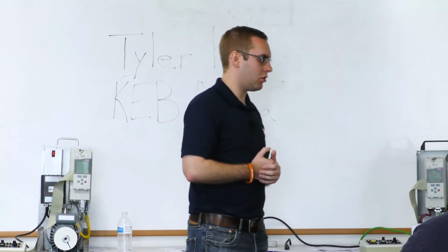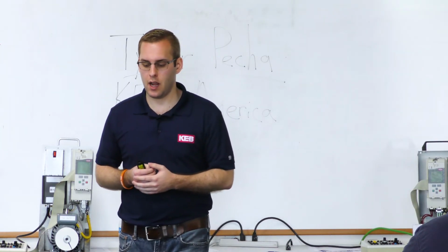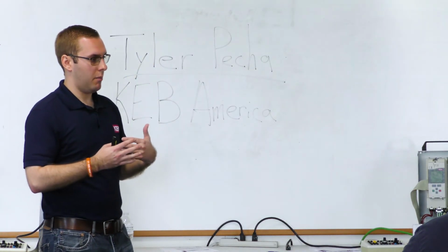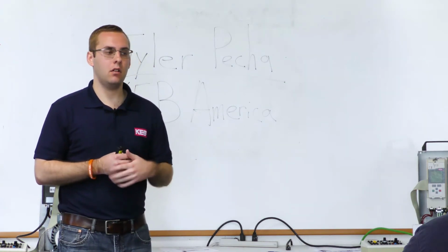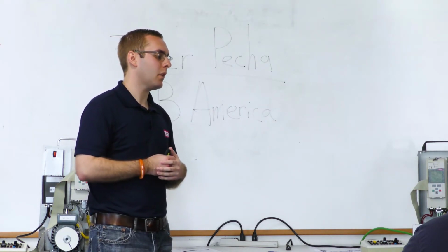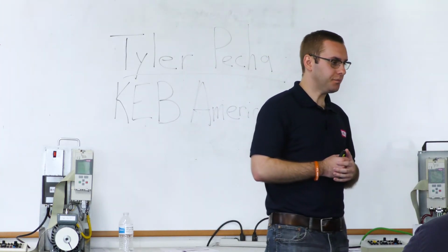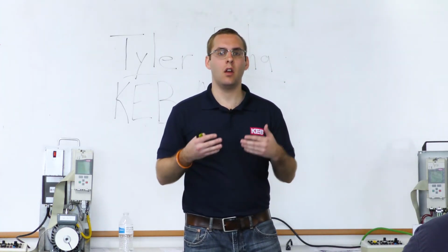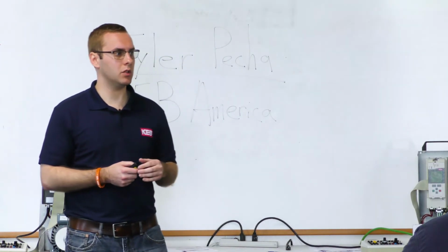For serial speed control, the controller is going to write a direct RPM value to the drive. So it's not looking at the machine data. So if you're going to make machine data adjustments or scaling of the serial pattern, that should be done in the controller. But if you are using something like digital or binary speed control, where the drive is in charge of the profile, then yes, you would need to look at making sure that your speeds are set correctly in the drive and your machine data as well.